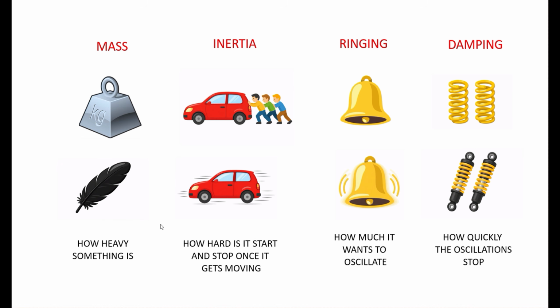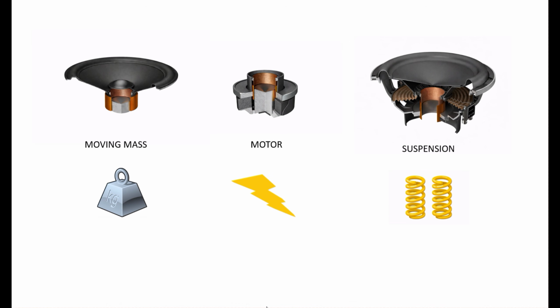Once again, when we think about our speakers, we're really talking about the inertia in the moving mass. When the cone's moving this way, first of all, it takes the speaker motor to get the cone moving, so the inertia in accelerating the speaker cone and getting it moving, and then changing the cone's direction. If it's a very heavy moving mass, then you need more force from the motor to get it started and to change the direction of the cone, compared to something that has a lighter moving mass, which will have less inertia.